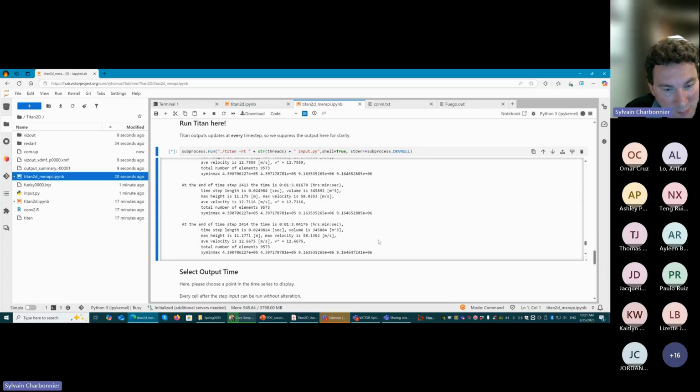So I'm almost at the end of the simulation now. And that's the other thing you want to check. That average velocity needs to be closer to 1 or 2 meters per second to actually say, okay, the flow has actually stopped, right? So you see here after 1 minute and 12 seconds, I'm actually getting an average velocity that is very low, like 2.8. So that's pretty good. And then I'm going to reach 1 meter per second here when the simulation is done. So that's good. So now my simulation is almost done.